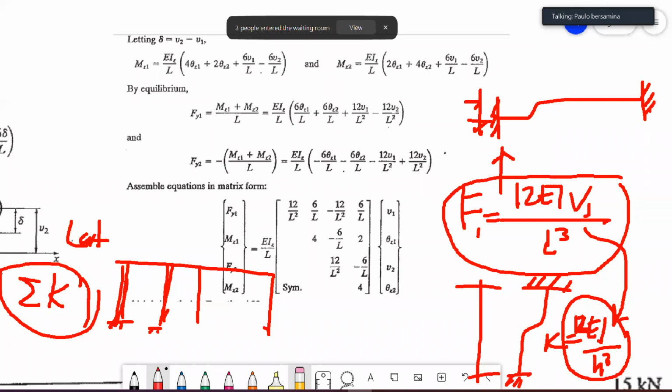That's why in STAAD, if you want to find a soft story, STAAD will sum up all the stiffness in a floor and compare it with the other floors, and if there's too much difference in stiffness, it will report a soft story failure. You know that in most of the last earthquakes that happened, soft story is the common failure. So my point is, that's how important this formula is. It is used in STAAD.